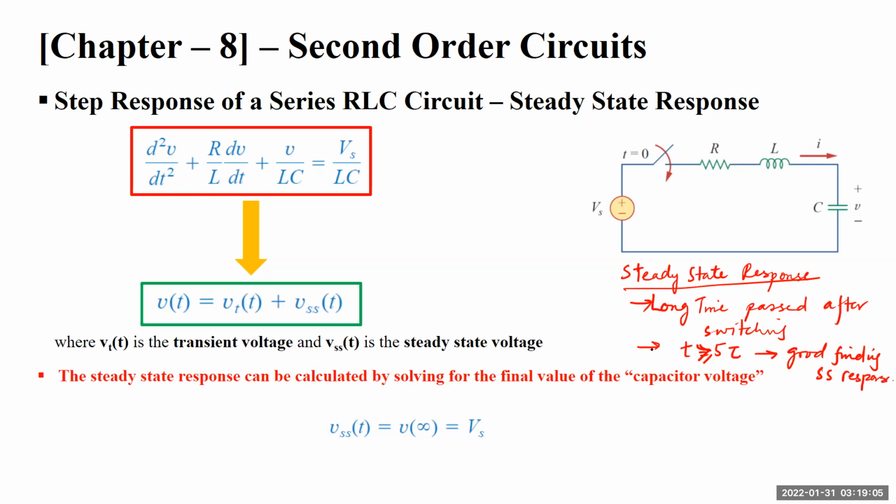Remember, this is more used in first order circuits. It is not technically a term for the second order circuit, but generally it means that your circuit has reached steady state. If there is an inductor involved, it means that the inductor has either completely magnetized or demagnetized. If there is a capacitor involved, it means that the capacitor will be either completely charged or completely discharged.